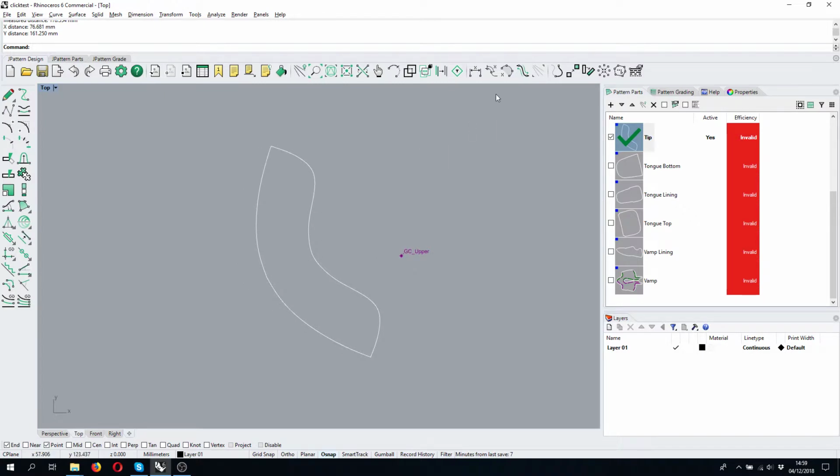This is pretty useful if I want to measure anything, or I can use my crosshair to measure a specific distance, and I can measure it and align it on whatever I want. And I can also measure the length on the curve. So in this case, if I select from here to here, I can see that the measurement is 207.4 millimeters between these two points.